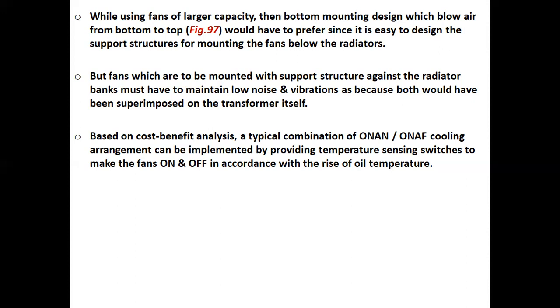Based on cost benefit analysis, a typical combination of ON-AN or ON-AF cooling arrangement can be implemented by providing temperature sensing switches to turn the fans on and off in accordance with the rise of oil temperature.